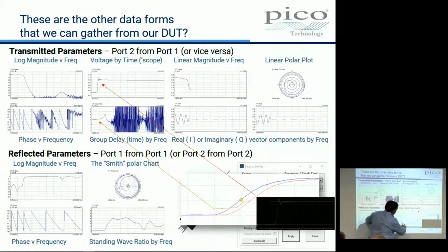Right, so with our low frequency scope, we were able to see this 2 nanoseconds, weren't we? And we also saw it, although it's a bit blacked out here, on the Pico sample display, the TDT display. That's that 2 nanoseconds. I don't know whether you can see, that's 0 and that's 2. It's measuring a group delay of 2 nanoseconds at low frequency. In other words, all low frequencies are delayed by 2 nanoseconds.